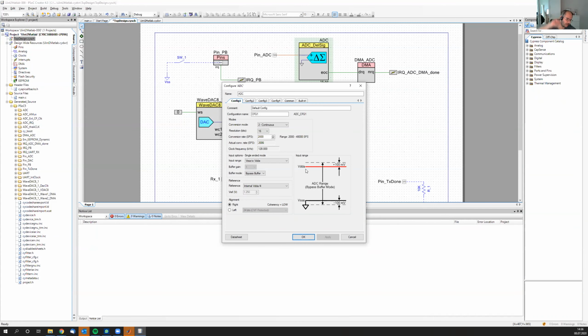But just one question into the round. So how could I, for example, produce a reference voltage on a circuit? Because we're system-driven hardware design, we build a system, okay, we have the problem, our ADC is inaccurate and we want to supply it with a reference voltage. How could we create one on our circuit? Basics of electronics, think about it. Which component can give us a very good voltage, a fixed voltage?